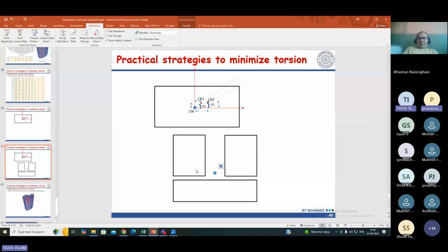See, here the condition is that a common corridor is provided. The structure will be separated only when the corridor is not provided. So either to satisfy the condition you can avoid the corridor, or the corridor can be provided, but that corridor will be on the expansion joint.